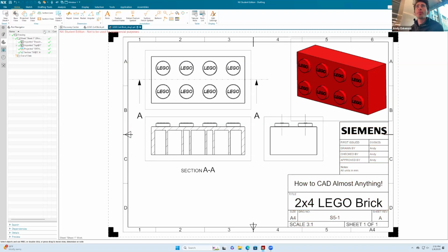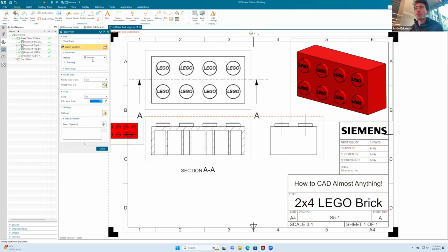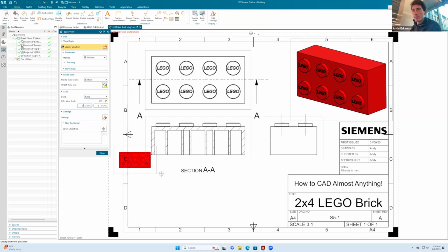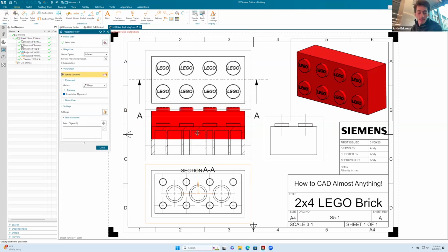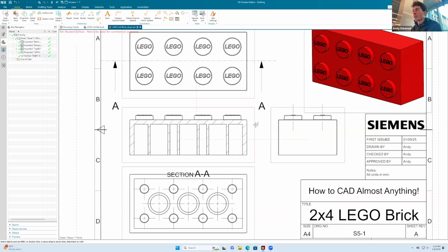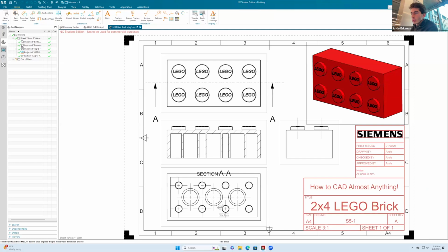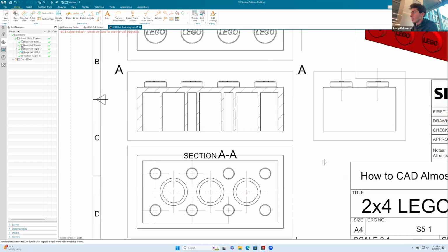Okay, this is good. Now I just want to bring another base view, which is the bottom view. This is also going to be ratio 3, and I do want to make it related to that one. I'll say okay. So now, yes, we're going to start adding a number of dimensions in here. I'm just going to get rid of some of these lines.